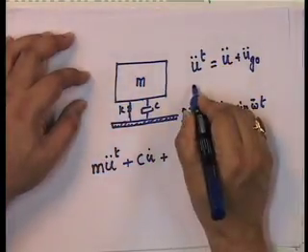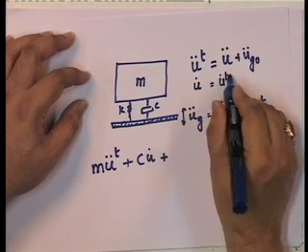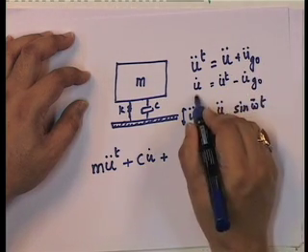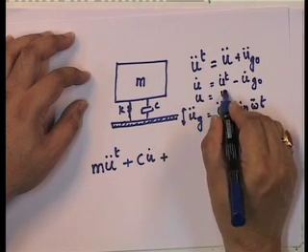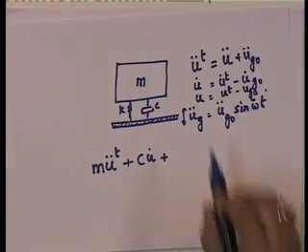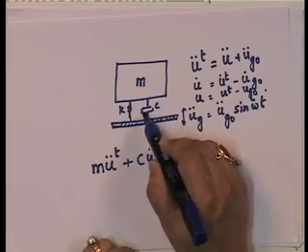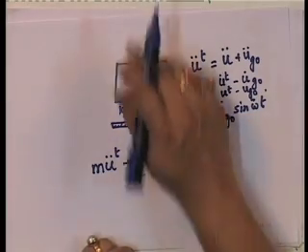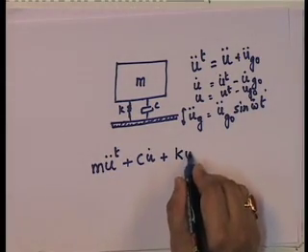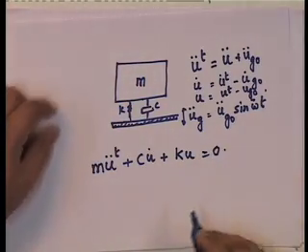So, in other words, u dot is actually the total velocity minus the ground velocity, and u is equal to u total minus u g 0. So, the spring and the dashpot see the relative motion, the mass however sees the total motion, and therefore this is equal to this plus this, and there is no excitation on the mass. So, this is equal to 0.